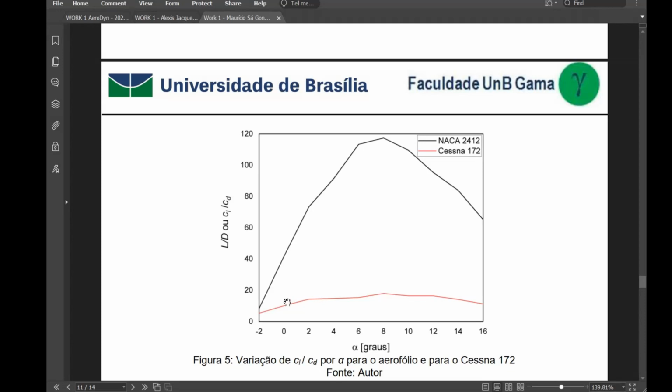And here is the lift and drag coefficient for a complete airplane that uses this airfoil as the profile for the wing. It's not obligatory to put, but if you found such data, you also can compare. You can see that the airplane is very different from just the airfoil because it has all the structure around, right? Fuselage and other equipment. You remember that at the end of chapter 1, we had a comparison of additional external equipment around the airplane that increases drag coefficient by almost 50%. So this is one such example.